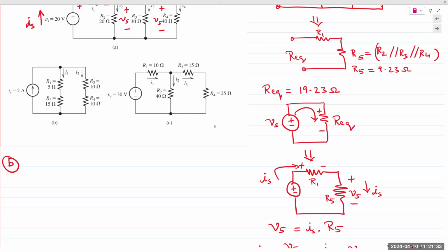You have a current source of 2 amps going down this pathway. And then it splits into 2 branches. Look at those branches. You have R1 and R2 in the first branch. Are they in parallel or are they in series? What's the value? Second branch, current splits into 2 branches. Both branches are an equal split. What's the value of I1 and I2? That's it. But let's look at the step-by-step analysis using our technique.